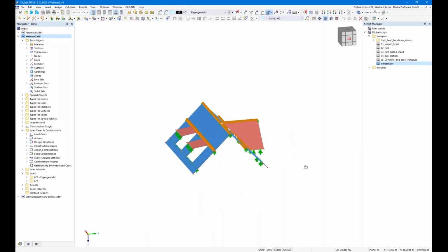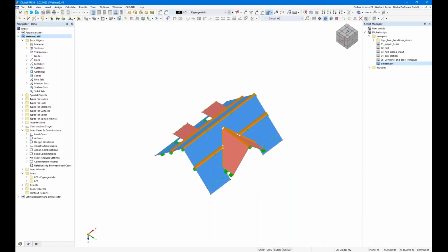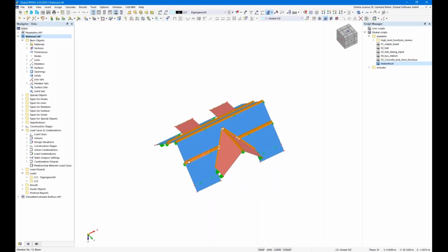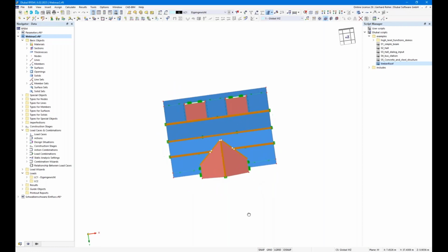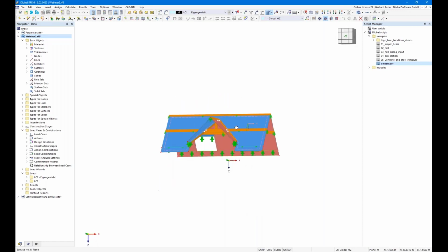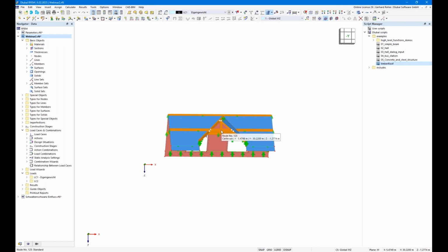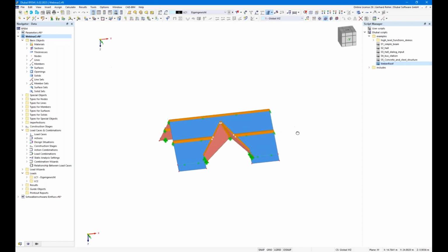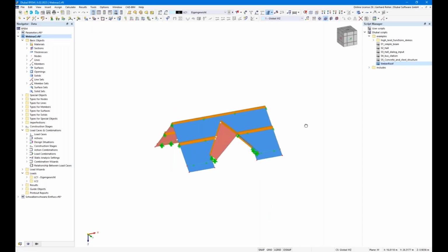And the question is always how to get the loads on it easily. Is it on the safe side to design the purlin with the whole load from this rafter, for example, or maybe when this building here is taller, then of course maybe this is design giving, because this gives you a nodal load here, or it gives you a nodal load here in the purlin in the center. So that's always hard to get a good approximation.